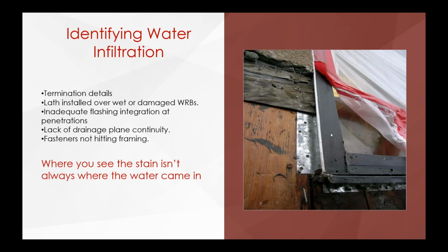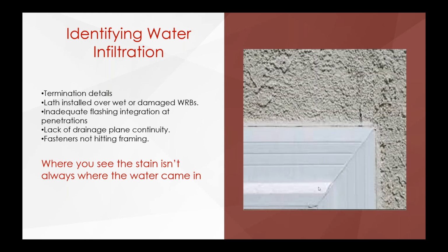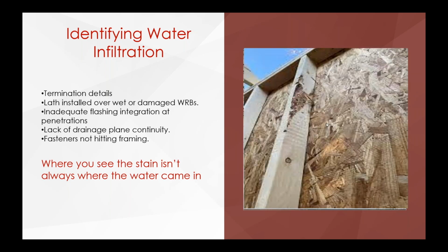Same thing here. I mean, we've got a short flange casing bead right here. We got paper right here. That could just wrap around. Now it comes down and it got into the exterior. You can see the damage down here in the sheathing. I'd always be looking for head flashings. Here, right here, you see no flashing here. They attempted to do some sealant right here across the top. You can see it's already separated, but again, no flashing there, so you'd be looking for that.